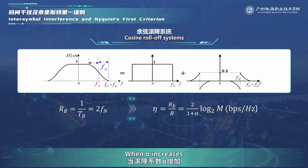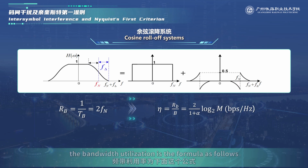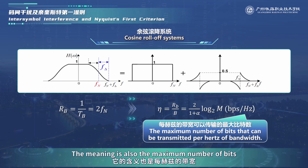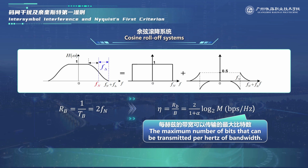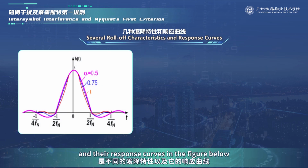When alpha increases, the bandwidth also increases, and the bandwidth utilization decreases. RB is the symbol rate, and if it's a multi-level modulation system, the bandwidth utilization is given by the formula as follows. The meaning is also the maximum number of bits that can be transmitted per hertz of bandwidth. We can see the different roll-off characteristics and their response curves in the figure below.